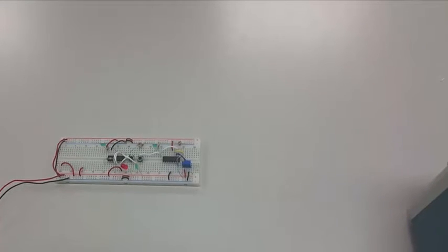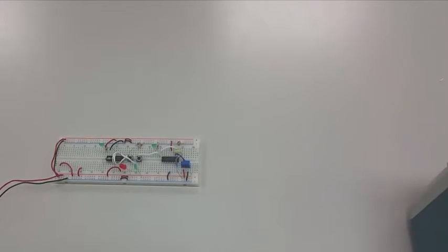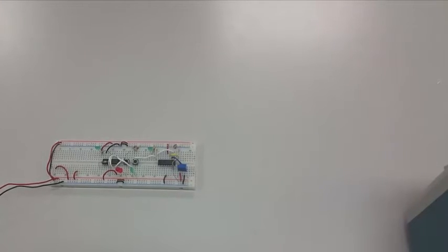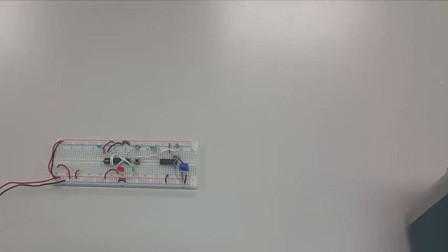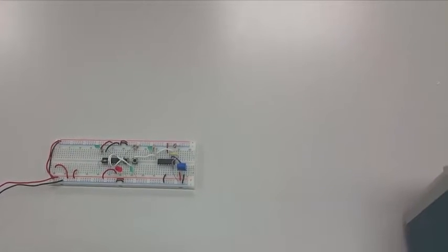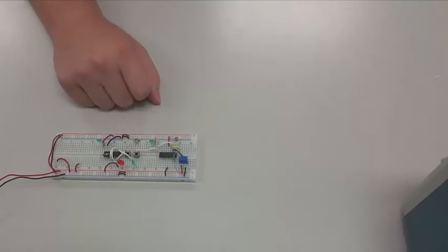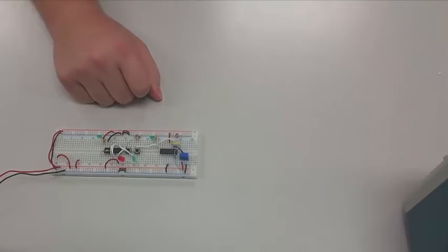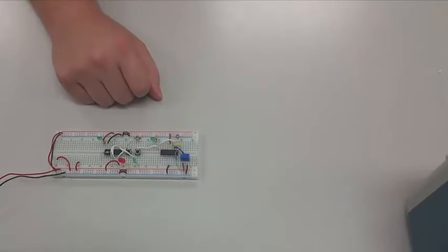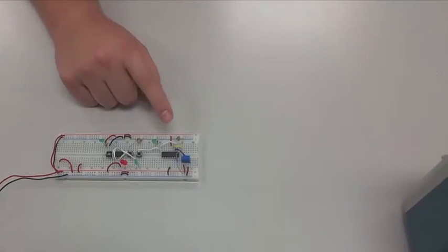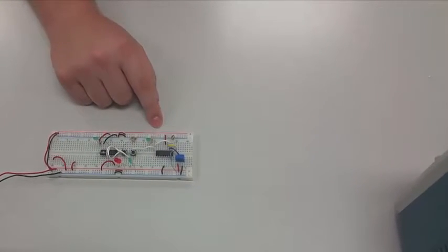When troubleshooting subsystem 2, the first thing that you need to do is make sure that the circuit is working properly. To do this, you're going to check both push buttons and then check the output from the first subsystem. We have noticed that the first push button for subsystem 2 is not working. So now we are going to go ahead and make sure that the output from subsystem 1 is coming through properly.